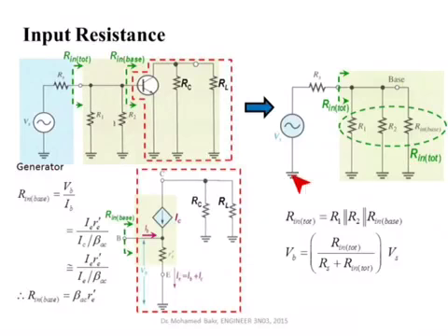Now we got rid of everything to the right of this transistor and replaced it by the equivalent Rn base. So now we have something called Rn total. Rn total is simply the parallel combination of R1, R2, and Rn base. R1 is given from the circuit, R2 is given from the circuit, and Rn base we already calculated, depending on the numbers, between 900 to 1500 ohms.